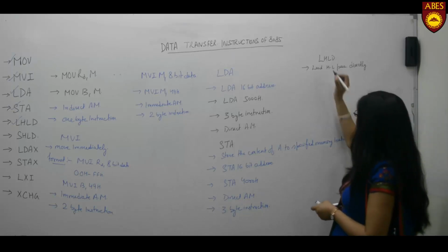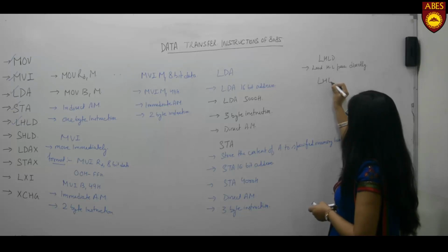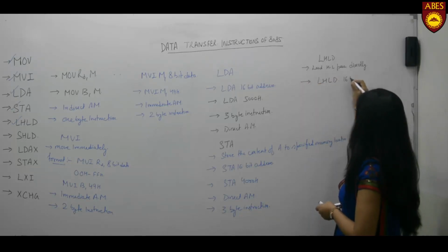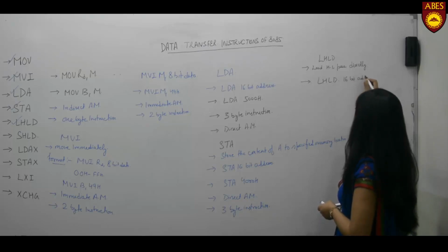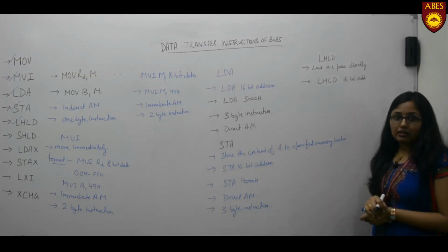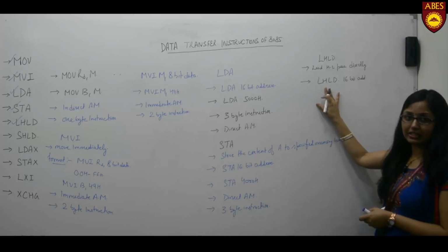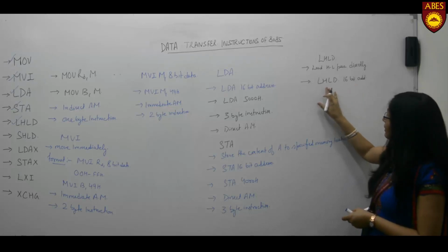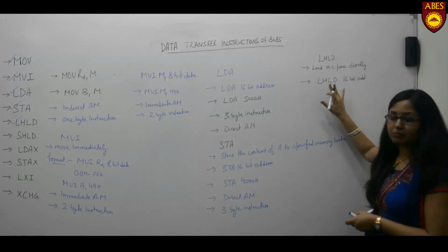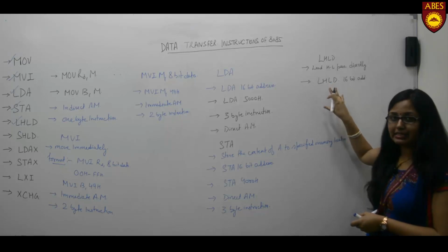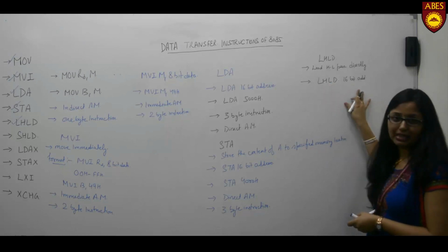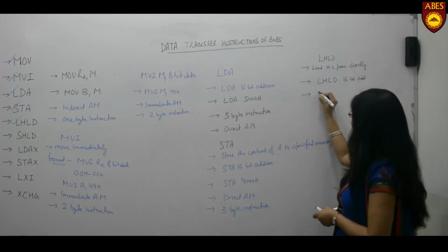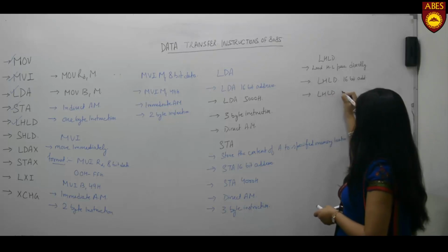What does this instruction mean? The syntax for this instruction is LHLD 16-bit address. This is basically used to load the HL pair with the content of the address which is mentioned in the instruction.